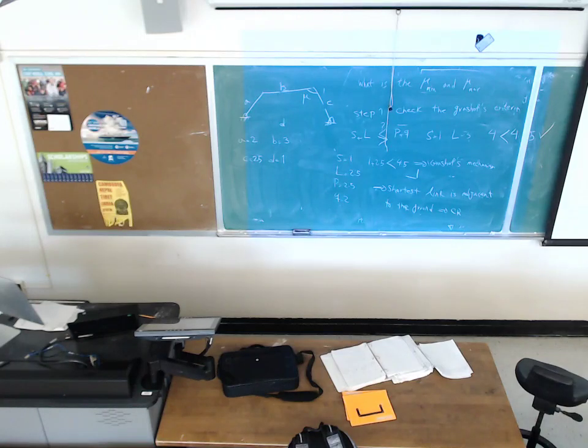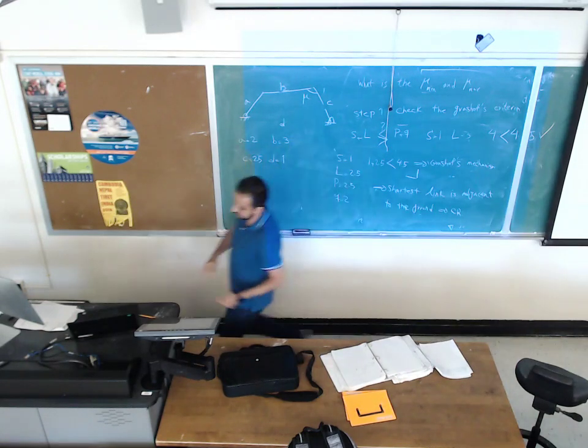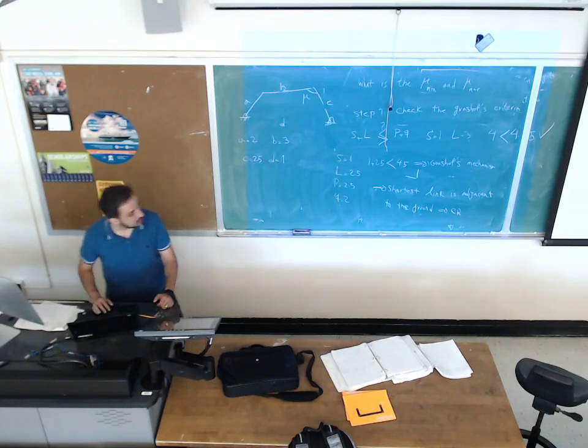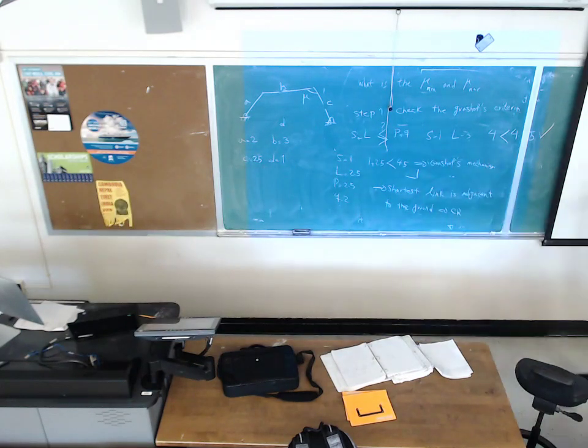Still, minimum transmission angle, this is the transmission angle. It's occurring when theta equals 0, and the maximum transmission angle is occurring when this one makes 180 degrees. So if it rotates, when the red one is making 0 right here, when the red one is at 0 degrees, this angle is going to be the minimum transmission angle. You can use the same equation.